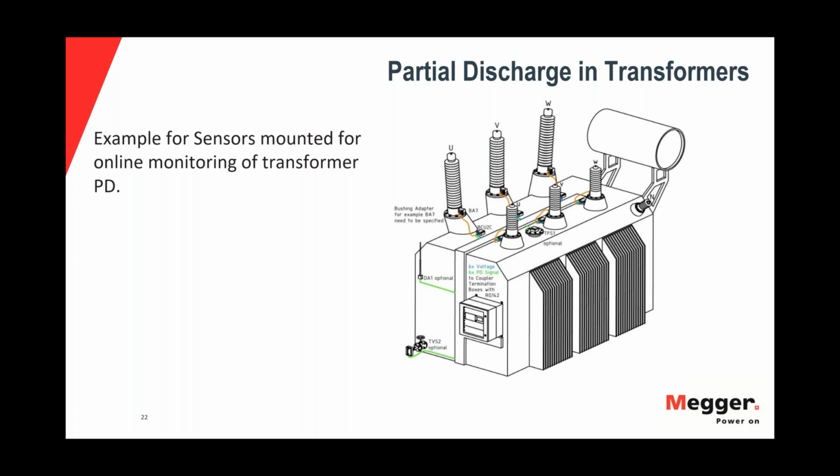While also measuring at higher frequency, it's less susceptible to the normal noise of the substation, which usually happens at low frequency. But still, for this type of measurement at bushing taps, we have an adapter called a disturbance antenna, which picks up the corona noise, and then it subtracts that from the measurement. This is one of the big benefits of our system, called gating, which means it can measure the noise and subtract it from the total PD measurement, which gives a cleaner result.